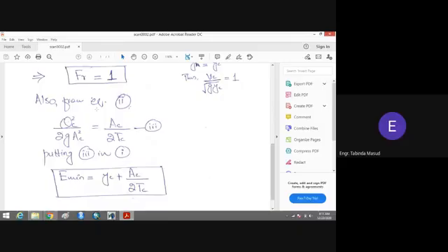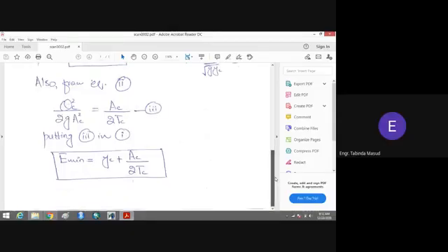Okay, if we divide both sides of equation number 2 by 2, then what will you get? You will get this equation number 3, and if you put this equation number 3 in equation number 1, you will get this term: minimum specific energy is equal to YC plus AC divided by 2 into TC. AC is the critical area of the flow and TC is the critical top width of the flow. So this is the equation for minimum specific energy.